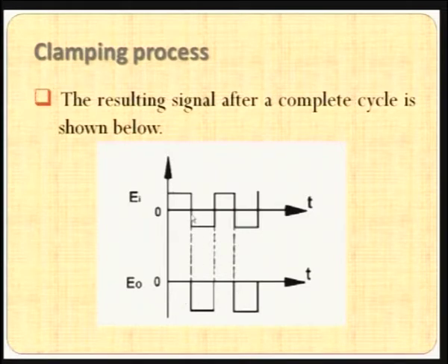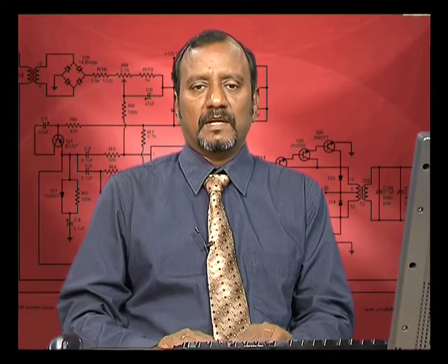Because we have taken a digital signal here, we should not misunderstand that the positive or negative part is removed. It is not happening here, but it is shifted. So, the oscillation is happening with respect to a negative voltage in this case. So, this is the operation of a negative clamper.